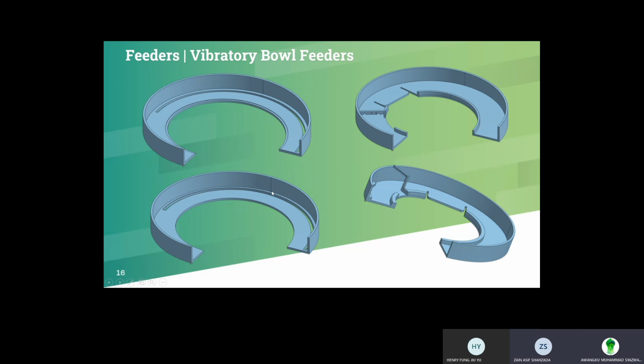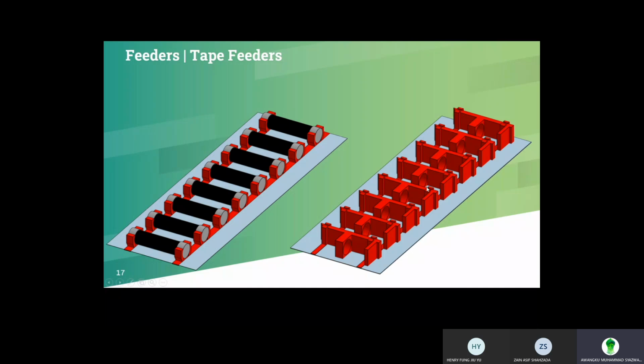So we are using gravimetric principles to make them fall down into the slots. Here we're using deflectors to ensure the casing comes in the correct orientation, and some slots or traps to keep the opening upwards. So the ones facing downwards will be thrown out of the track.